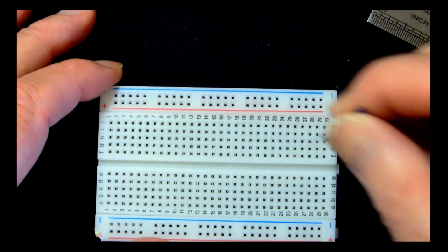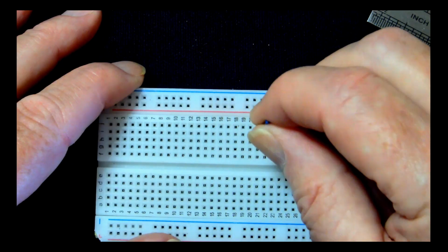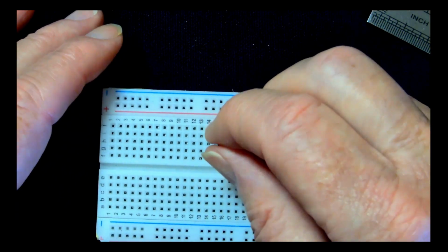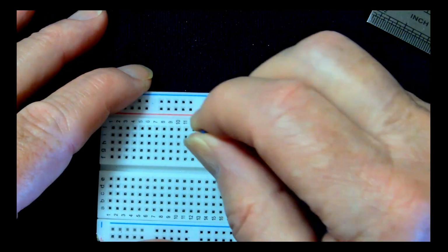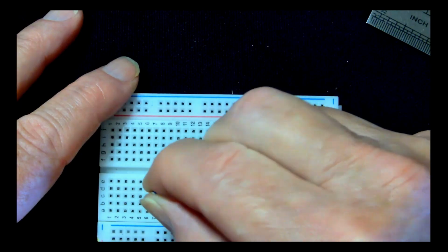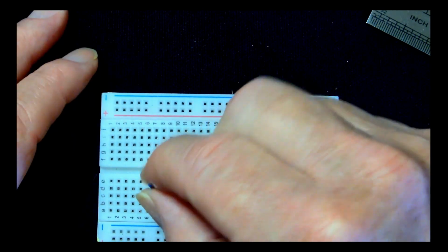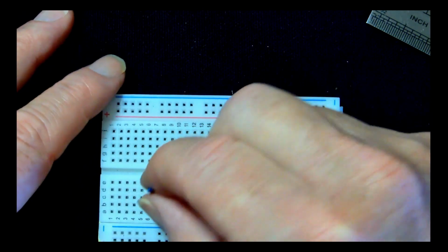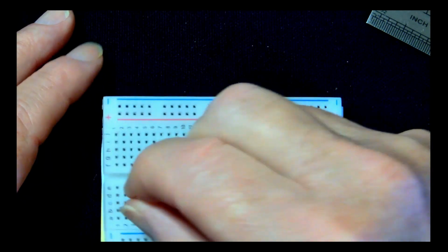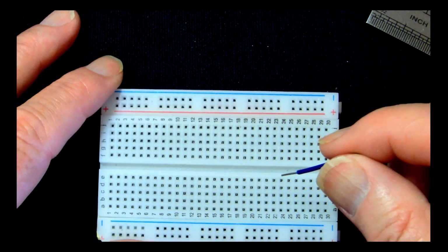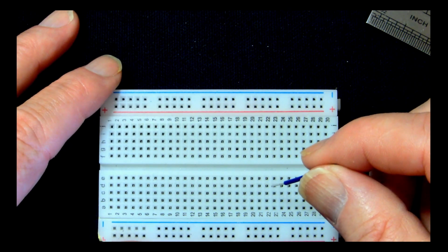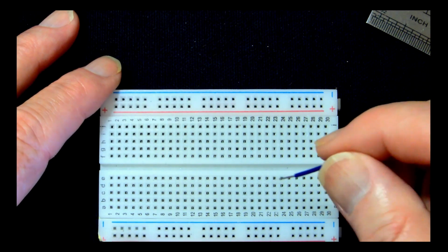And let's just randomly push it into sockets. So you make sure that there's no obstruction to you. It's not failing to go in because the clip has been put in sideways slightly, or it's bent or buckled, whatever. And in every case, I should be able to pull the board up, suspend the board. That's how much grip there should be. Now, the tolerance on these holes, from reading quite a lot about it now, is between 0.4 of a millimetre and 0.6 of a millimetre.